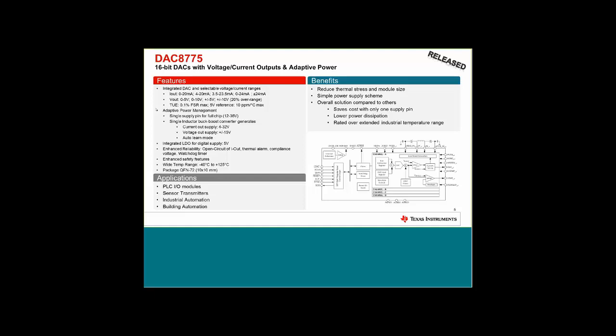The next question is, how fast can the DAC be changed over its full range of 16 bits? So that relates to the previous point as well. It depends if you were talking about something in full tracking mode or in one of the clamped modes. If you were to go from the full-scale range of plus minus 24 milliamps for the current output, this is the worst case. It takes about 2 microseconds to slew from minus 24 to plus 24. If you were doing one of the unipolar ranges, something closer to 1 microsecond, which is also true for the voltage output.